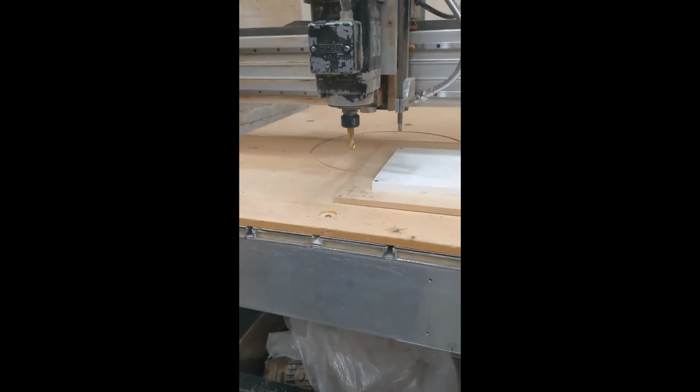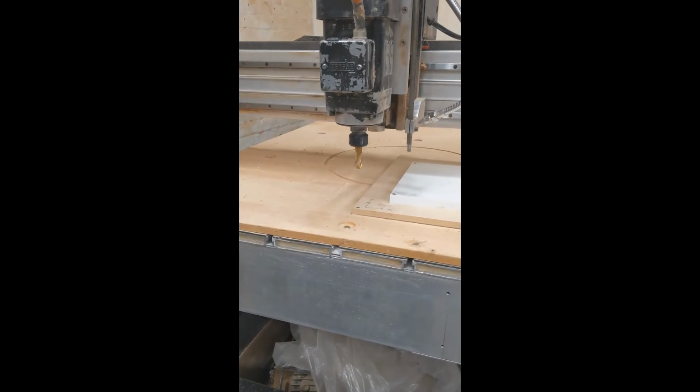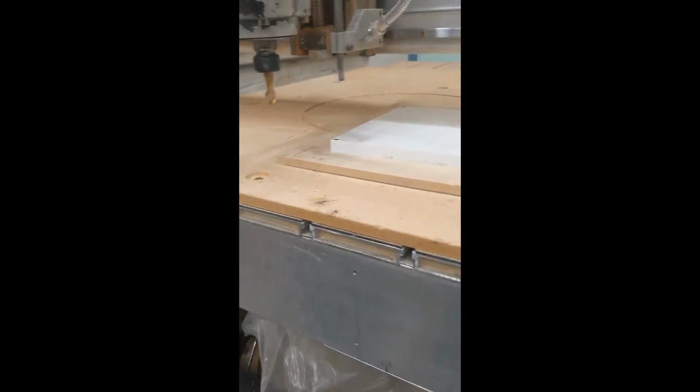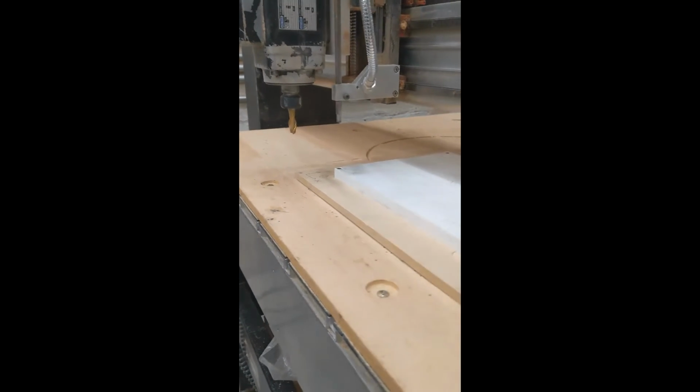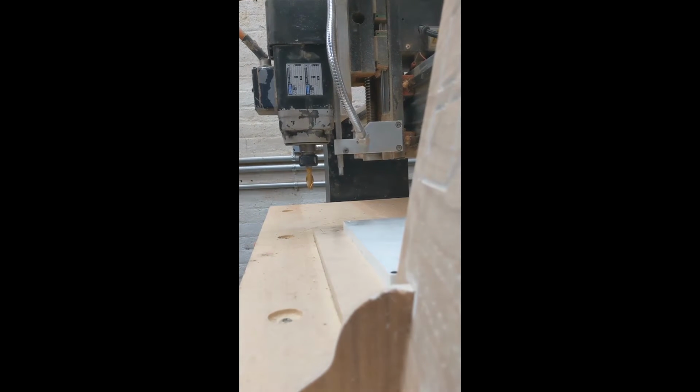You really have to do these sanity checks, unless you've run a part a million times, to make sure all your zeros are correct. In this case, my X and Y 0 again are on the bottom left of the MDF. I don't really need to worry about where my stock is there because I've modeled that all in 3D relatively accurately. It's mating on that top surface of the pocket, which is pretty accurate because I milled it with the same end mill that I'm going to mill my part. Hopefully all that makes sense.